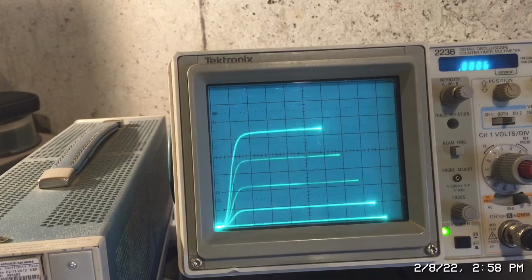So now if I do the calculation, I'm at 5.5 milliamps, and I still have my same 40 microamps, but now my gain is only 137.5. Let's call it 138. So you can see that even between transistors produced by the same manufacturer, you see quite a bit of variation.